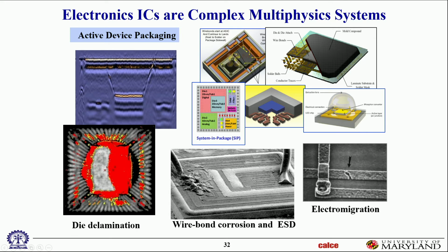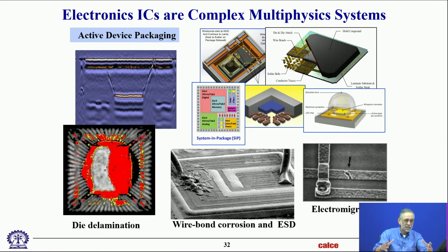So what happens is, again, because moisture gets in the package, and because the lead frame is metal, that expands like a metal does. The coefficient of thermal expansion is roughly about, depending on if it's copper lead frame, low 20s parts per million per degree C. But the plastic mold compound is much higher. Actually, these are special plastics that have been tailored for low CTE, but it's still higher than the metal. And repeated shrinkage and expansion will eventually delaminate that interface, and that's what you're seeing here.